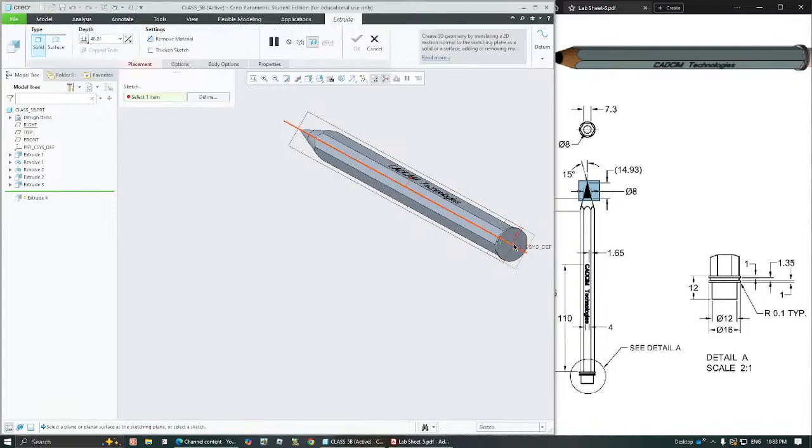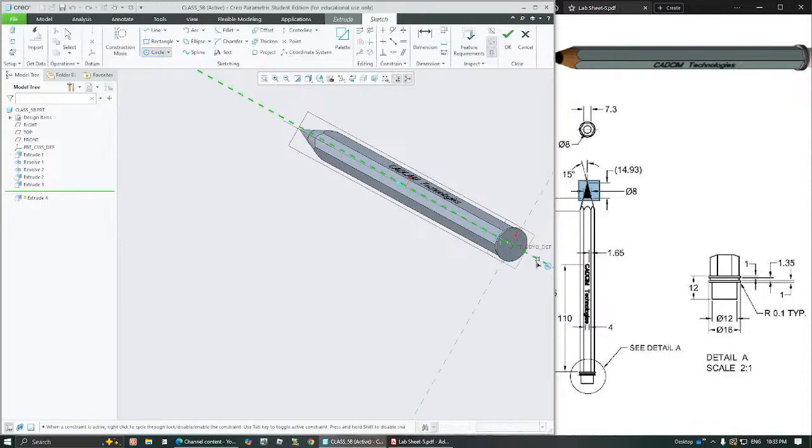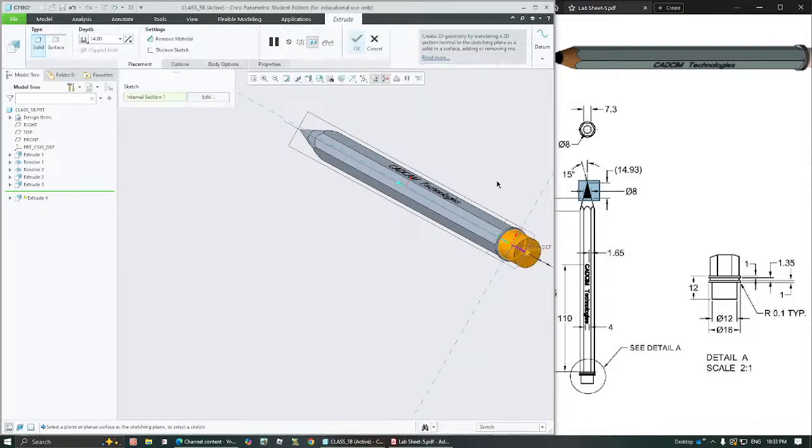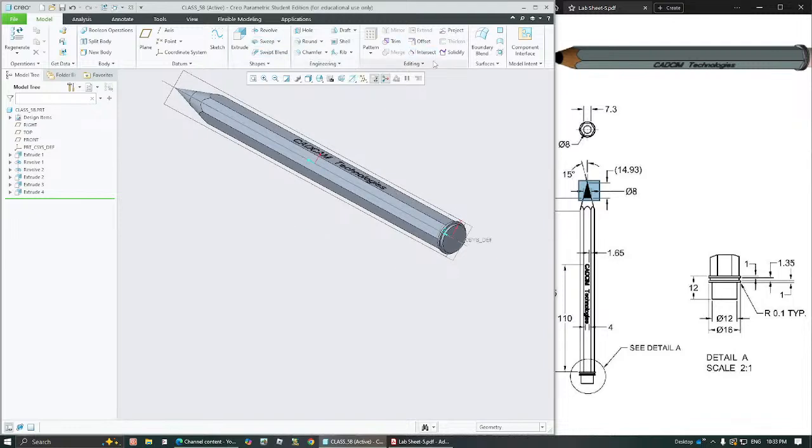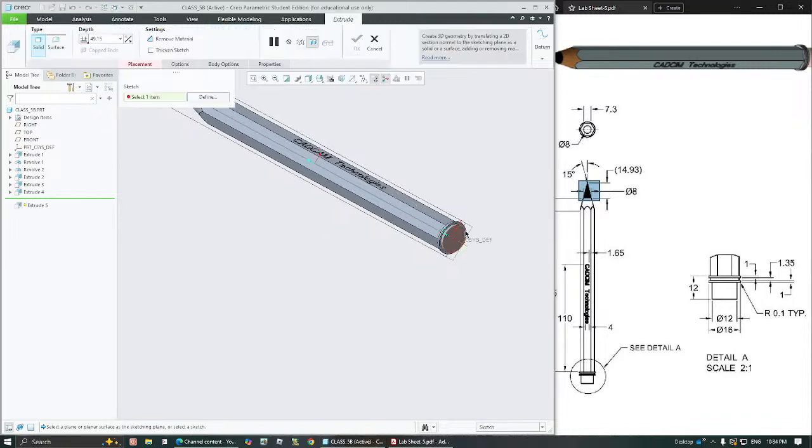Okay, so I'll go for extrude again. Select this surface, take one more circle. This time this middle one is slightly less than that, but how less? I think it's 1 mm less. Let's go ahead with 16 as the earlier one, minus 2. That should do. Extrude this by 1.35. Click OK, and then we'll need it once again, so go ahead and select one more extrude.